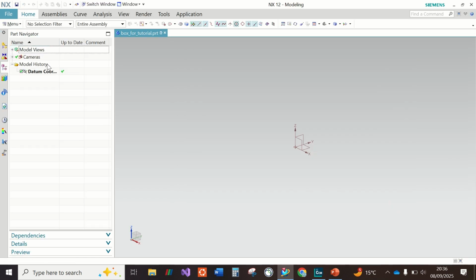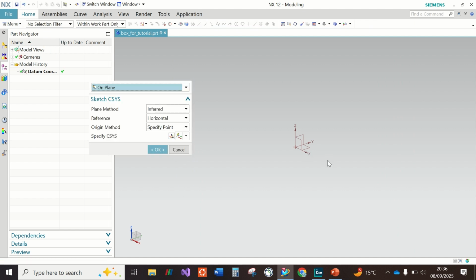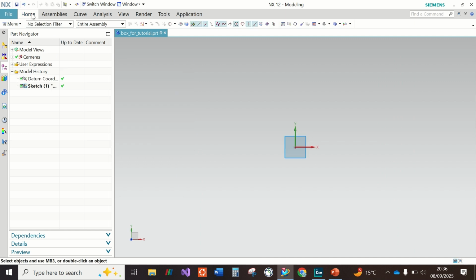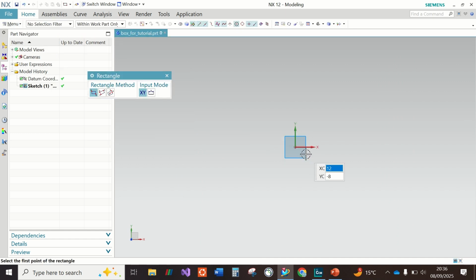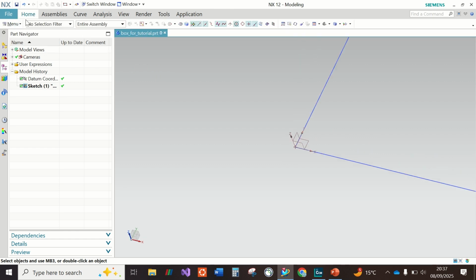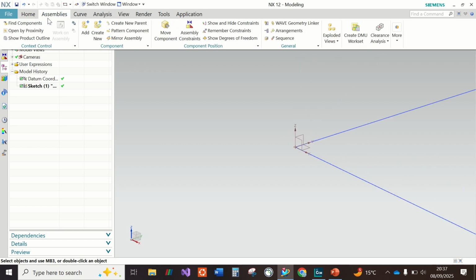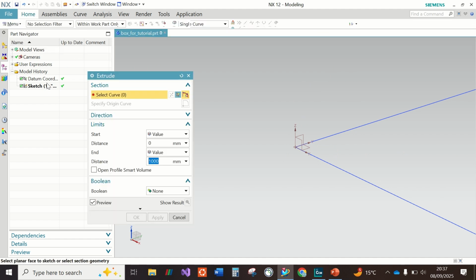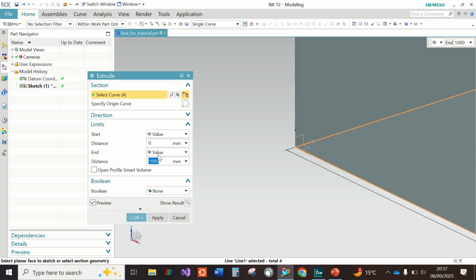a simulation. So I'm starting here with how to do the CAD. I'm just doing a very simple box on CAD. The CAD software I'm using is called NX12. As you can see here, the dimensions are 1000 by 1000, and this is just because this is in millimeters, and I would like it to be 1 by 1 in STAR CCM. NX defaults to millimeters, while STAR CCM defaults to meters, hence why I've got it as 1000 here.